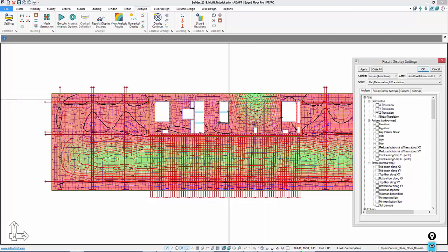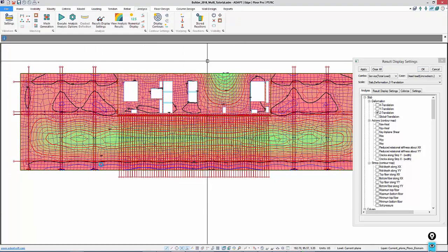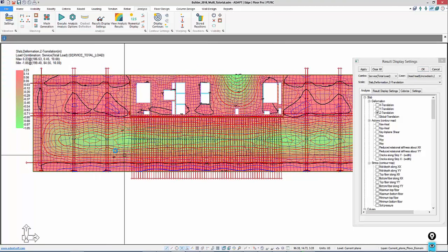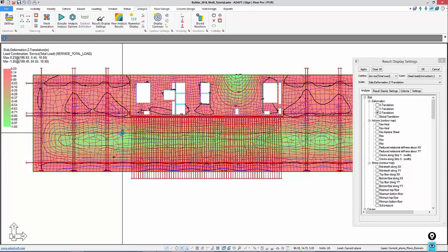This is kind of part of the core. We might add some PT along this beam just to control that deflection. So we're mainly concerned about the deflection outside of that core region. And we can see that the deflection along this contour line here on the inner zone of this region, where we have the one-way slab transitioning into more of a two-way slab, is roughly 0.63 inches.